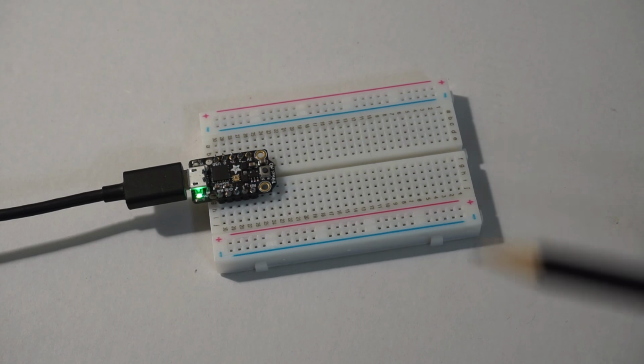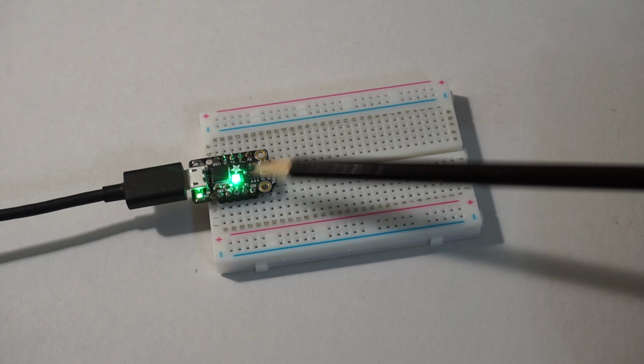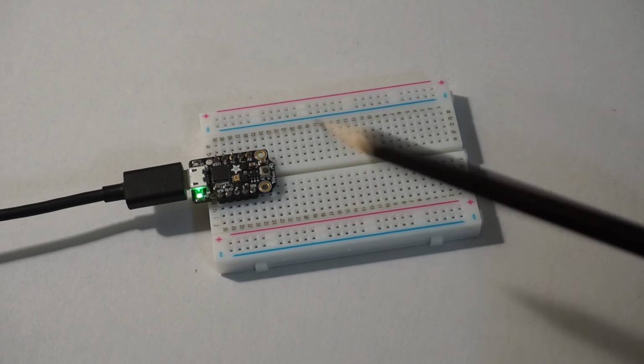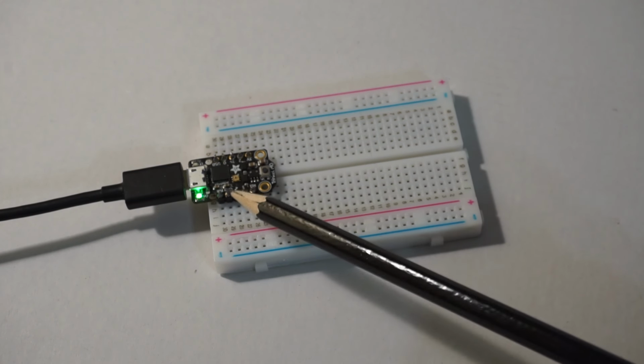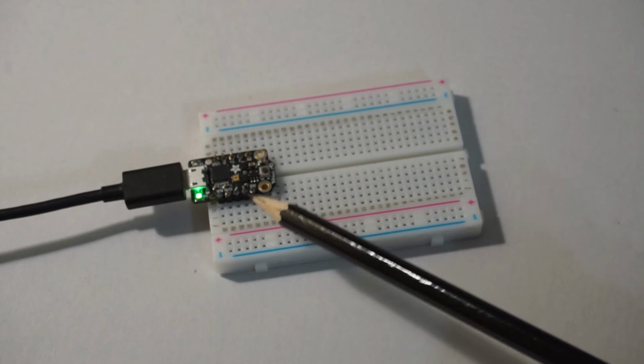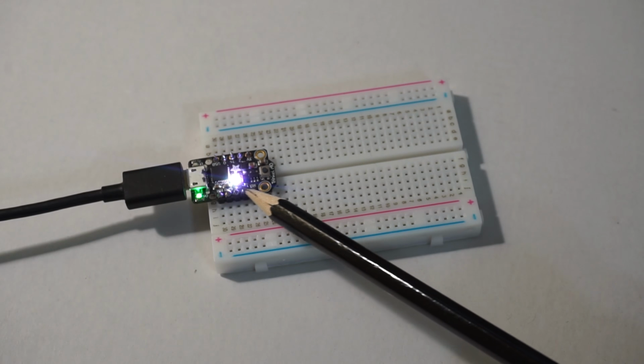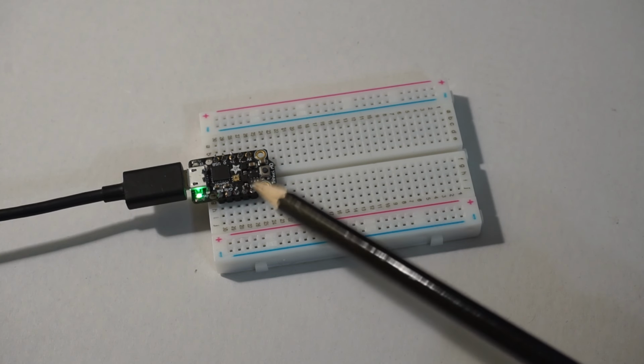As we can see, the red LED is not flashing, and this multicolored LED is doing some crazy stuff. Now, the first one is always green. That tells you the program is booting up. The next color is the error. In this case, it was white. If you notice that, here is green and then white. And then after that, it tells you the line number.